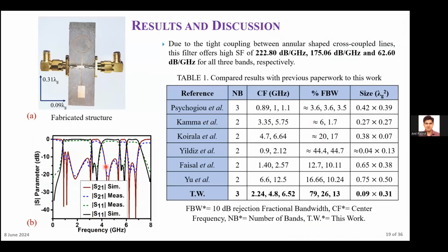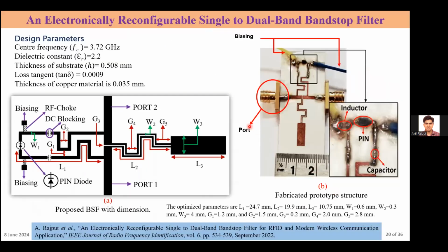And it is also fabricated, and it offers a 3 band stop response, which has center frequencies of 2.24, 4.8 and 6.52 gigahertz, and fractional bandwidths of 79, 26, and 13%.